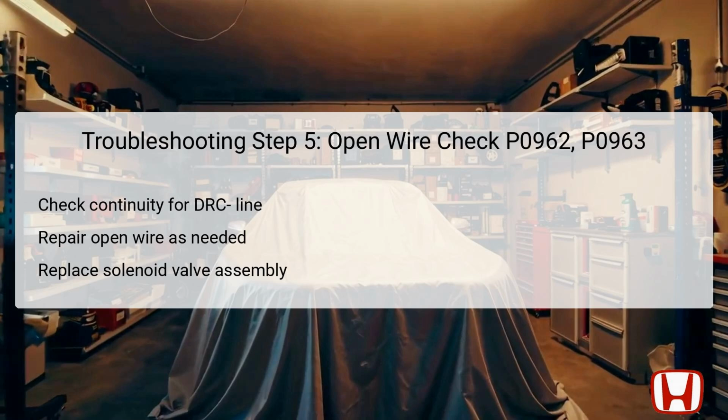A successful continuity check indicates that the DRC wire is functioning correctly, thus suggesting that if DTCs persist, the solenoid valve may be the source of the issue, warranting its replacement. If continuity fails, repair any identified open circuit between the DRC wire leading to ground or address any poor ground connections to ensure effective electrical flow. Troubleshooting this last segment is vital to restore the vehicle's transmission functionality, as well as to effectively eliminate the root